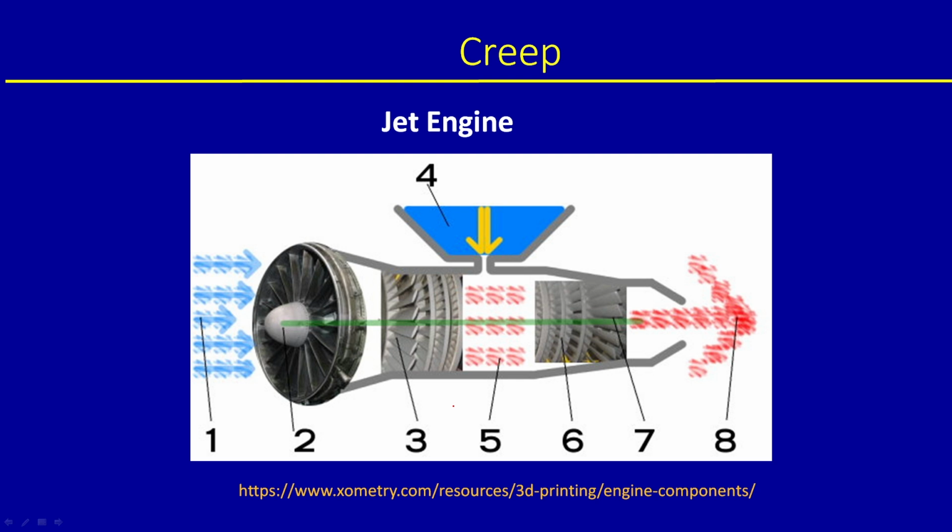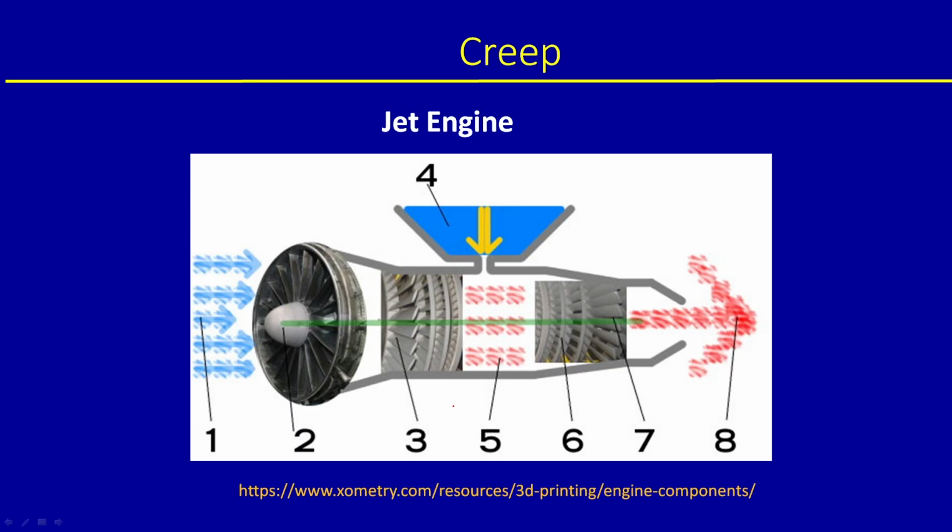Let us talk about solder alloys, which are used in electronic devices, like in mobile phones, cameras, or in computers or laptops or tabs. There the circuits are joined by solders, and we use lead in solder still today, and therefore, they can undergo creep at room temperature. If you do not cool them, they may break even at a lower stress. Many of the circuits break down because of mechanical stress. Your phone might have fallen down on the floor and then starts not working, because some solder joints might have broken.